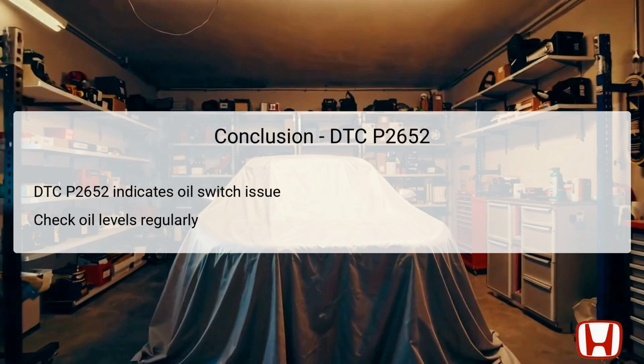In summary, DTC P2652 points to a malfunctioning rocker arm oil pressure switch in the Honda Civic models from 2016 to 2021. Understanding the role of the rocker arm oil pressure switch is crucial, as it directly affects the engine's variable valve timing (VVT) system.